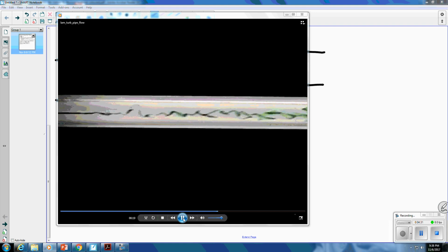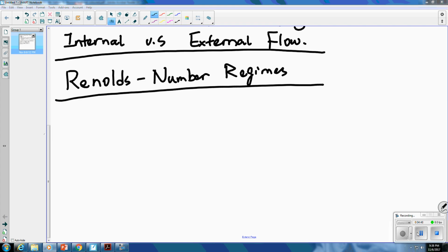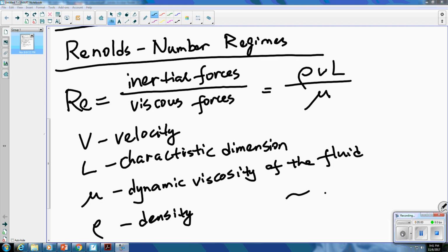And keep going, we increase the flow rate even larger and larger, and finally you see all the dye just blur into the surroundings immediately, right? So you cannot define any line here. So here we showed you three different Reynolds number regions actually. We haven't talked about it, but let's talk about Reynolds number and three different regions.